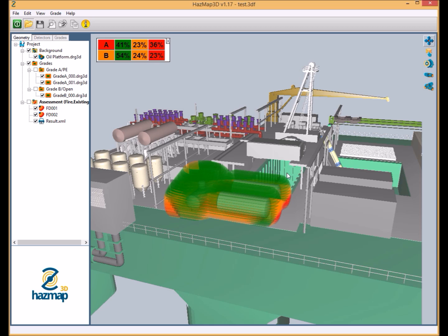There are a number of targets which must be set in the lead up to carrying out the gas detection mapping. This includes the analysis of potential explosion overpressures in a given area, which will in turn provide you enough information to target a specific gas cloud. Tools such as CFD can be useful in the generation of a target gas cloud, for example using explosion modelling. However, Micropack would recommend avoiding the use of dispersion data as the sole method of placing devices, particularly in unpredictable environments. Of greater concern is the potential of placing devices based on some scenario-based analysis or consequence modelling, which generally looks at less than 1% of the credible scenarios in a given area.